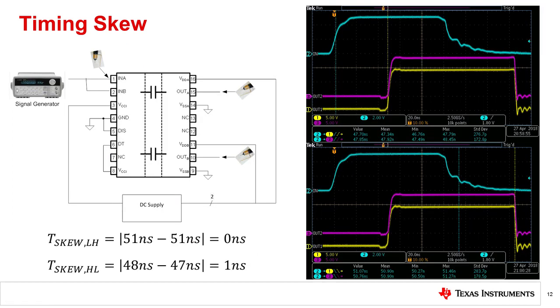To measure timing skew, an oscilloscope probe with a low inductance ground sheath should be placed at the input pin and the output pin of both parts or channels to be measured. All other conditions, including length of input path, should be equalized for a datasheet measurement, though for production testing, the conditions should be matched to the worst case difference in the application environment. Rising edges should only be compared to rising edges, and falling edges should only be compared to falling edges. All only for parts with the same part number, or channels in the same part. Again, statistical collection and persisting capture data can help to find the worst case values.